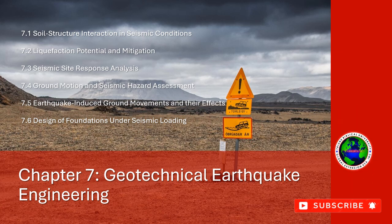7.1.4 Mitigation strategies for soil-structure interaction. To mitigate the impact of soil-structure interaction on structures during earthquakes, several techniques and strategies can be employed. 1. Foundation design. Deep foundations, pile foundations, drilled shafts, and caissons can provide better seismic performance, especially in areas with weak or liquefiable soils. Base isolation.